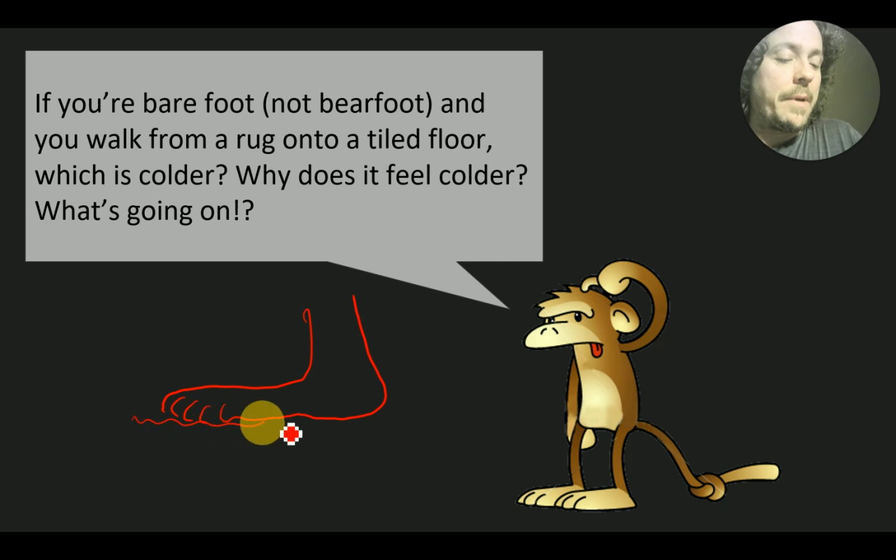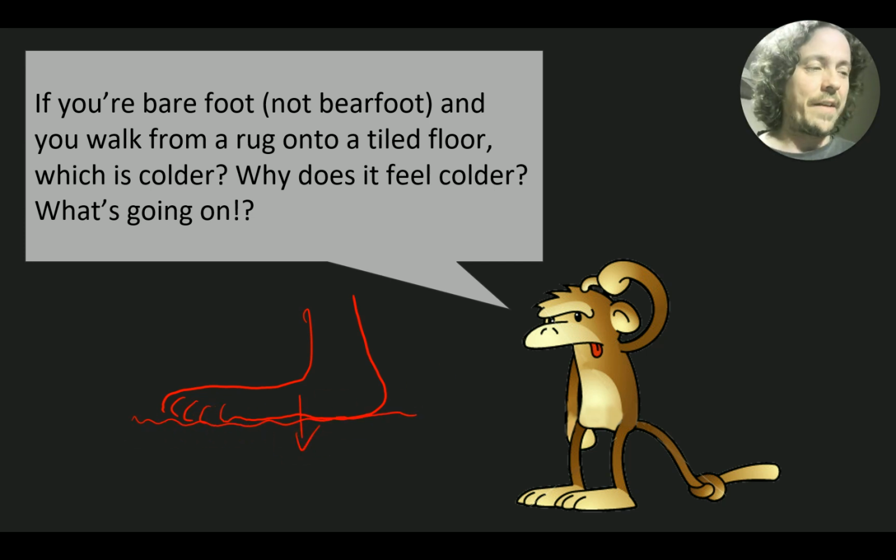Yeah, so if you're on carpet, the heat doesn't leave your foot very effectively. However, as soon as you step onto that tiled floor, the tiles are harder, they're denser, they're made of a more thermally conductive material. And what that means is that the heat in your foot, okay, your nice warm foot, leaves your foot and gets into those tiles really quickly. The thermal energy transfer is faster. So it's not that the cold is getting into your foot, as some people seem to perceive it. It isn't that. It's that the heat is getting out of your foot, making your foot colder. So yeah, that's how that works.